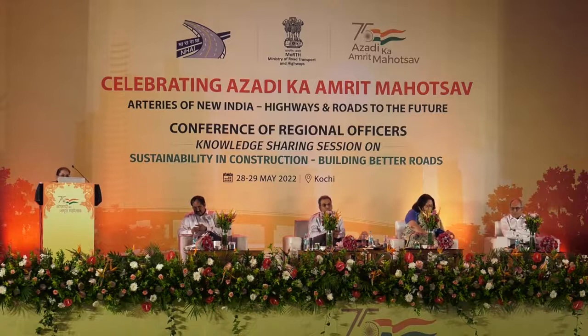People will ask why we say PMB 82, because temperature never goes to 82. But when we use this kind of material in airport runways, the impact it takes and the amount of load it bears make it a need. And the only benefit is that when you are laying a PMB road, you can lay just a 25 mm layer on the top of the road and everything will be taken care of.